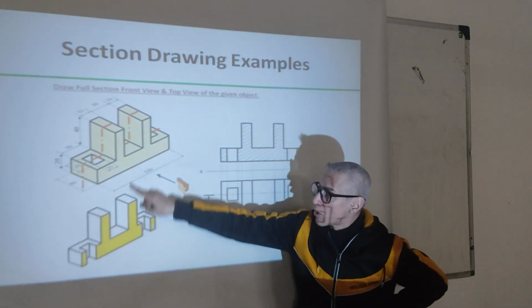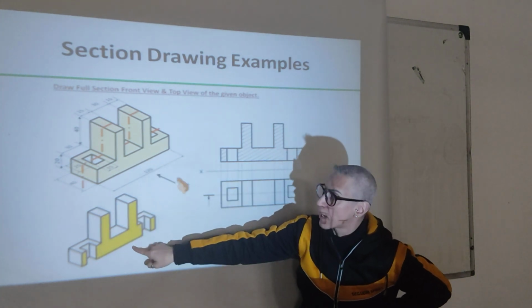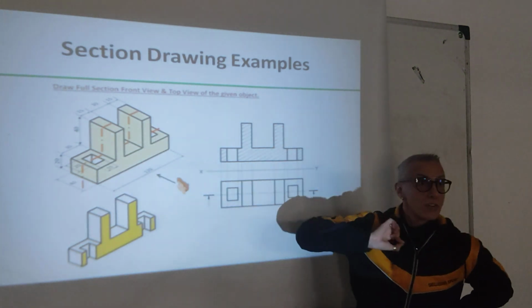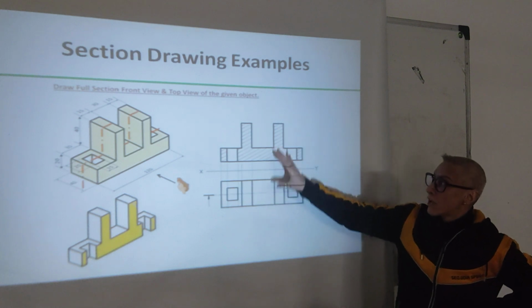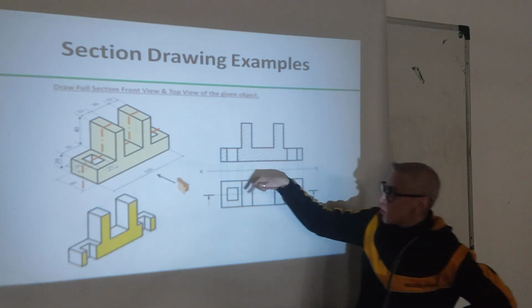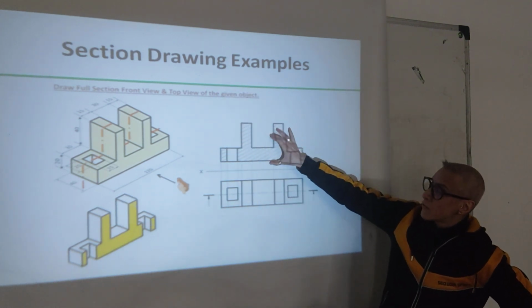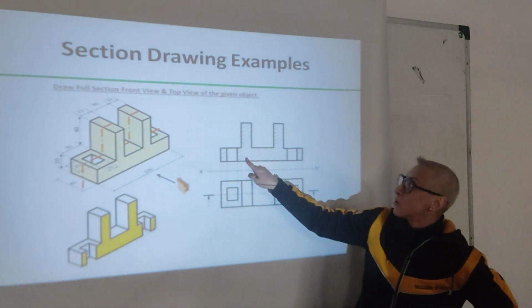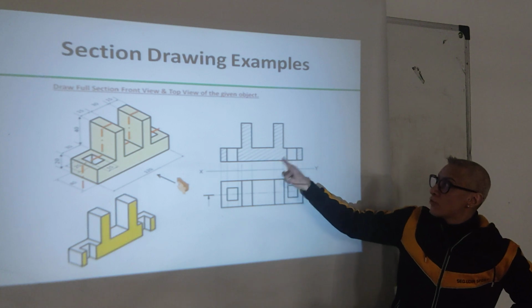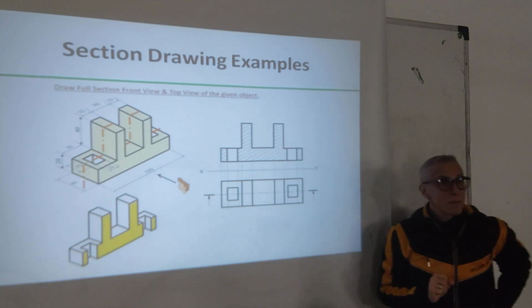If you look at the same drawing, which is an isometric, it will look like this after we remove this part, okay? So this part here, when we draw it from the top view and then rotate it as a front view, this is what we will see here. This is the solid material, which is hatched at 45 degrees, okay?